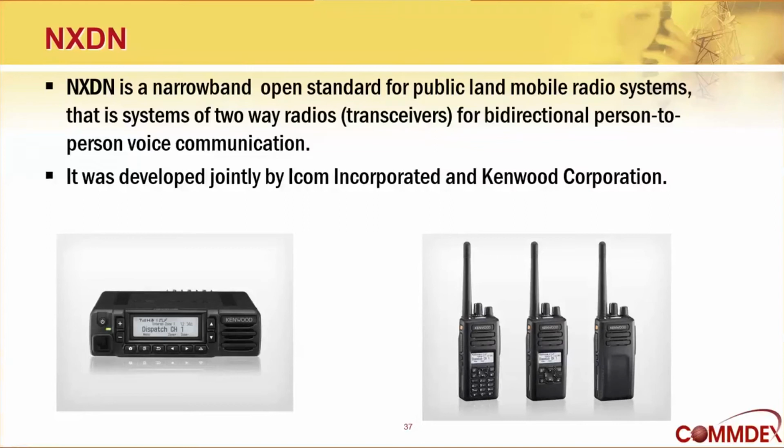And the last technology I'm going to talk about is called NXDN. That's the newest player on the scene. It's narrowband. It's an open standard. It was developed specifically to go narrower than the other technologies. It has the capability to operate in two different modes, either a 12.5 kilohertz bandwidth mode or a 6.25 kilohertz bandwidth mode. NXDN was developed jointly by ICOM and Kenwood, both Japanese manufacturers.